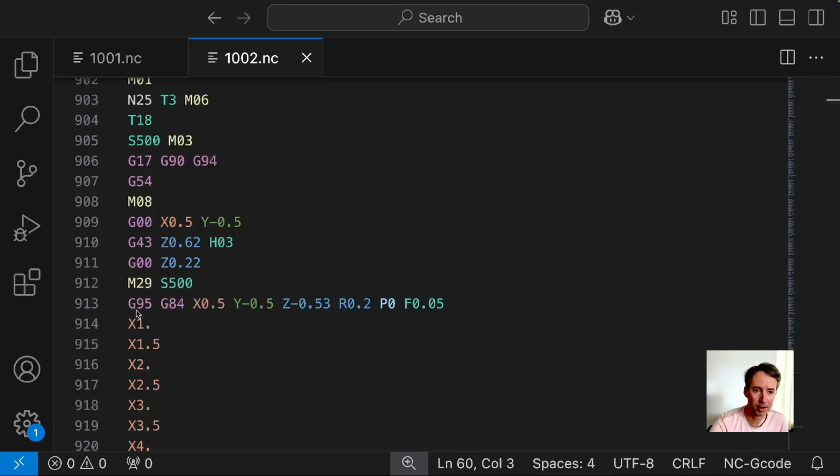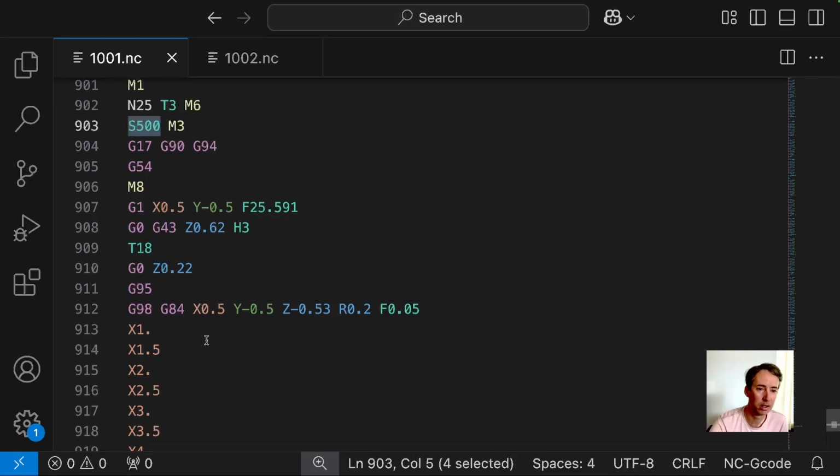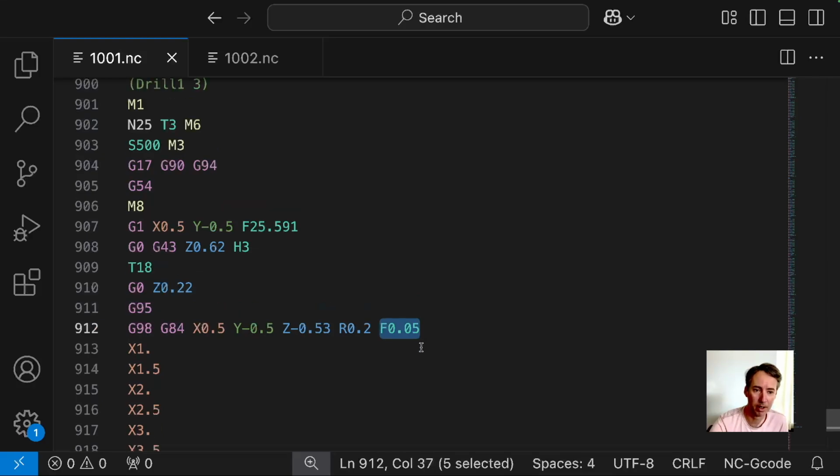The benefit of this is you don't have to calculate your speed and feed precisely. The feed is just the pitch, so you can use any spindle speed and your feed is still going to be this. And then here's the Haas style, where G95 is active and you're using your pitch as your feed rate. So just a little bit different way of doing it. Some people prefer one or the other. There is no right or wrong, but maybe you have a preference.